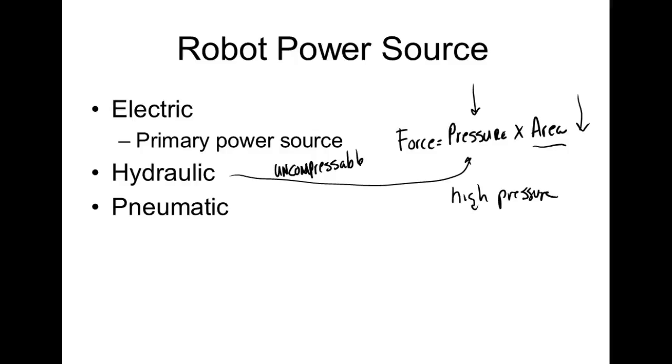We knew a guy that got into a pinhole in a hydraulic system, and when he hit it, it went into his thumb, and that fluid got in there. Of course, it sealed up almost instantly, and he almost lost his arm because of that. He didn't, but he was lucky, because that fluid got into his bloodstream and caused all types of problems. So this stuff is dangerous. If you get a leak, it's oils, and oils are very slippery.